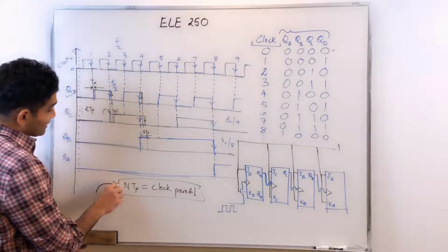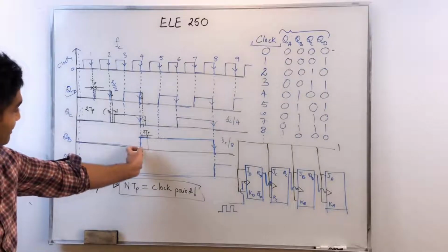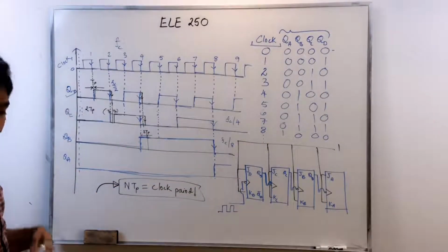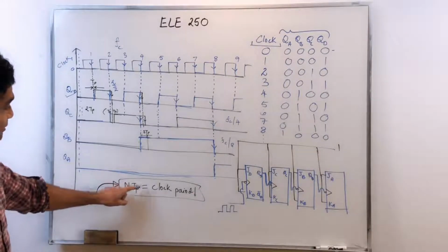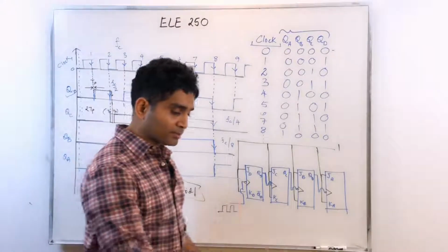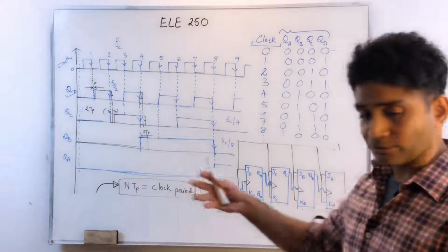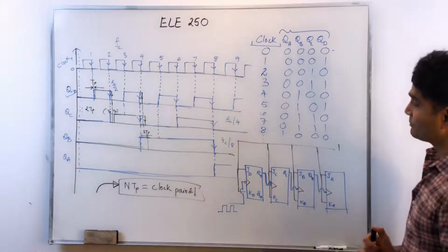But I have to live with this constraint when I'm working with ripple counters. As you can see here, this timing delay gets propagated, becoming larger and larger as more stages are added, and once this exceeds the clock period, I'll start getting wrong counts that can mess up my entire system. Mess up your clock, for example.